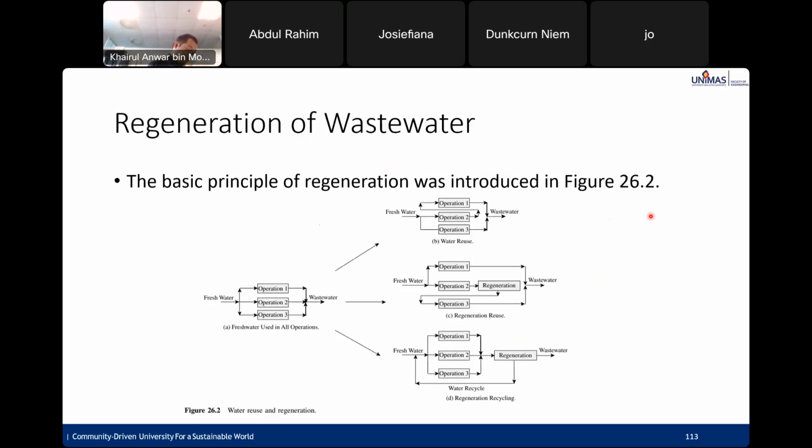For the design for minimum wastewater treatment flow rate, you have three design rules. Before you can design, you need to identify the pinch point. Any stream above the pinch must be treated. A stream with concentration equal to the pinch concentration must be partially treated, but below the pinch concentration, we can bypass the treatment process completely.